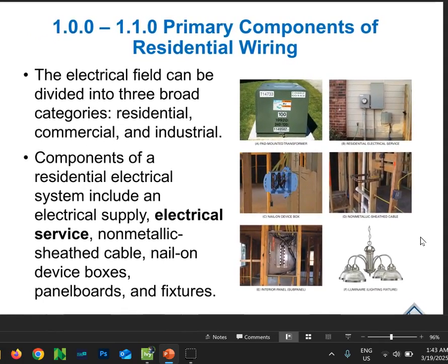We'll get into that a little later. Well, they have standards, and those standards require a minimum level of safety. Local governments and institutions can enact their own minimal standards as long as they're not below the NEC's. So Chicago and, for example, Gary, Indiana, they increased those standards, and the non-metallic sheath cable featured here is below those standards that they raised.